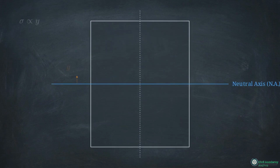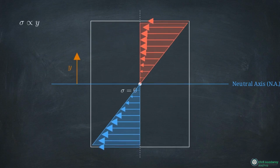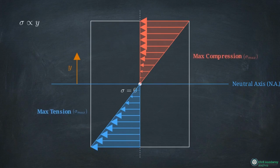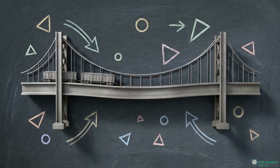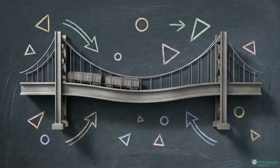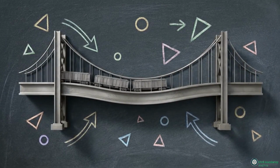Because stress scales proportionally with y, the stress is always 0 at the neutral axis, and it reaches absolute maximum compressive and tensile peaks at the furthest extreme top and bottom fibers. This equation elegantly unifies the applied external forces with the internal material stiffness and cross-sectional geometry into a single perfectly balanced framework.